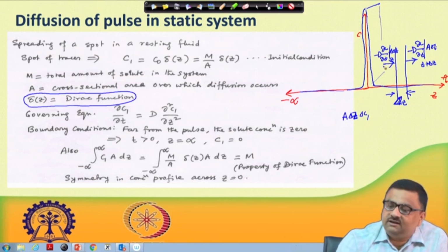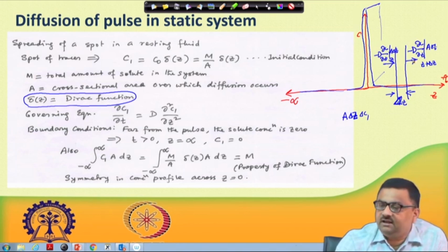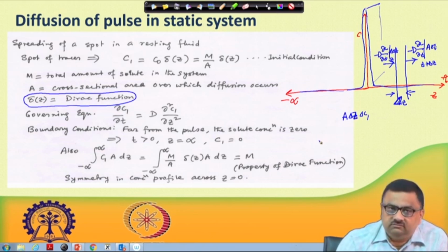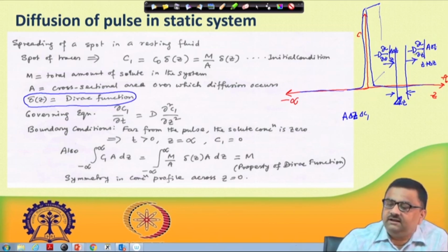In that case, here also, the number of moles that have gone in over duration delta t, and the number of moles that have left the system over this duration delta t, this minus this has to be the accumulation. Once we equated in minus out is accumulation, we took delta z to the denominator of the left hand side, and delta t from both these terms to the right hand side.